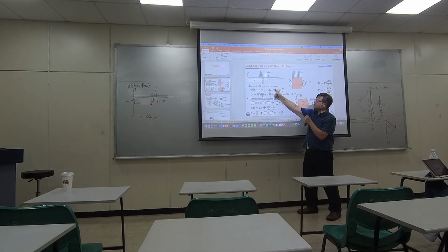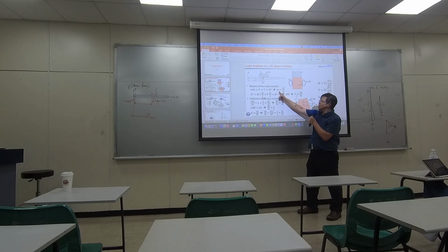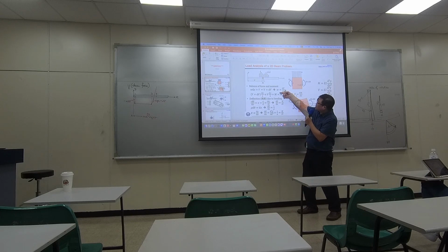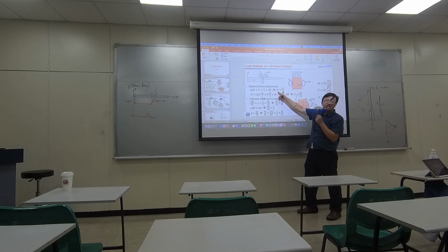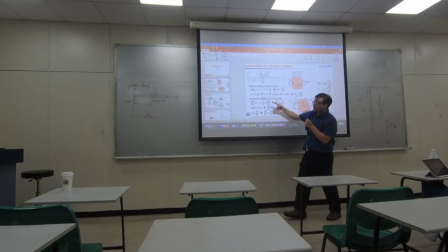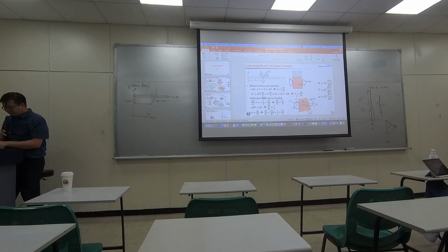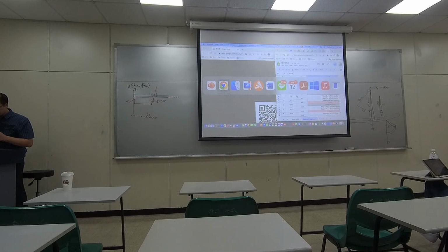If there exists a distributed load, when you move by a little, then your shear force increases by a little. And dV over dx, that's exactly the slope of the shear force. So this is telling you the slope equals how much distributed load you have. And since in that particular problem, we have constant distributed load,